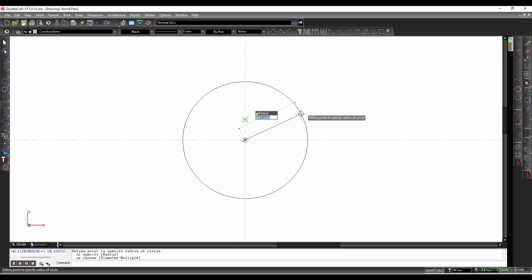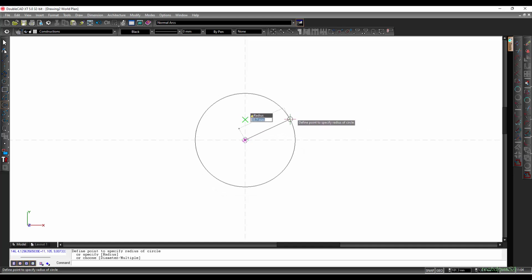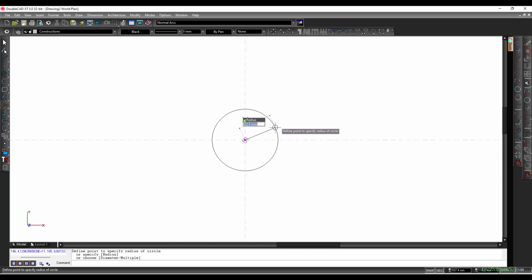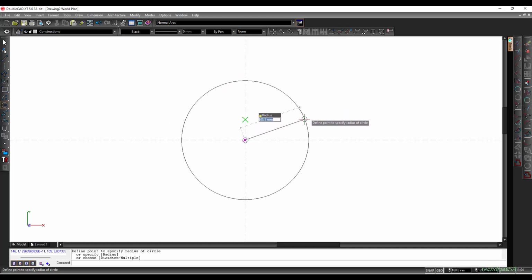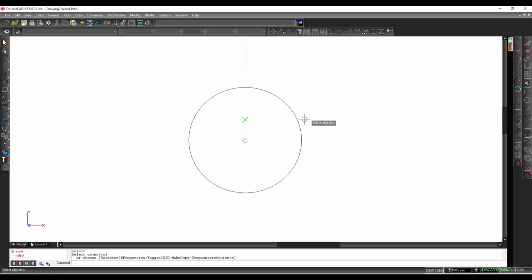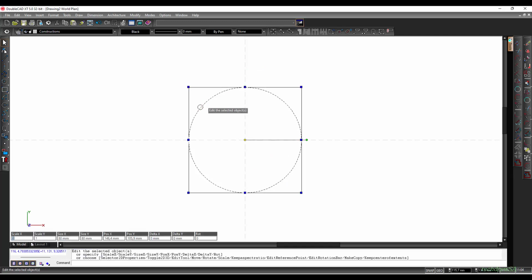Therefore, I'm going to select that, and I'm going to now see that because I'm using the circle tool, there is a box with the different dimensions as I pull on the distance. So I'm going to type in once, so tap once, and then I'm going to say I want the radius of the circle to be 40 because the total height of the octagon must be 80. And therefore I'm going to just press enter, and that will place my circle with a radius of 40 or a diameter of 80 millimeters.